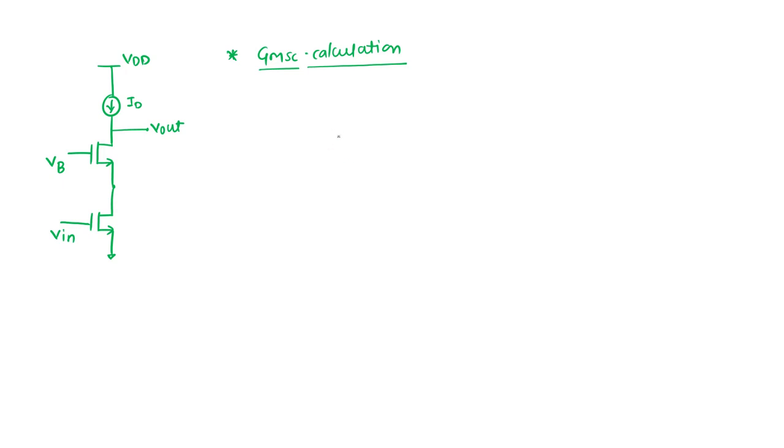If this is an ideal current source, we can open it, and for this Cascode device we can short the input. This is your short circuit output current, which we call ISC. The input signal we applied remains applied here, so we can analyze what the ISC is.